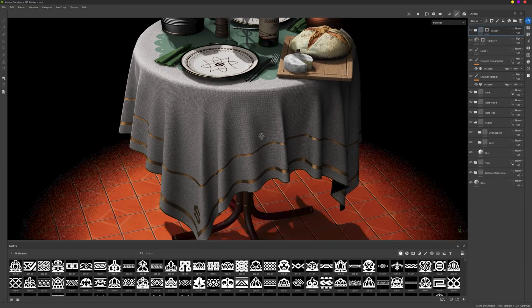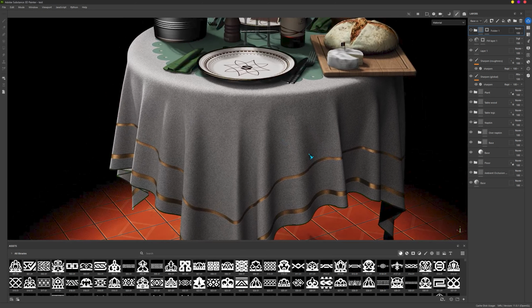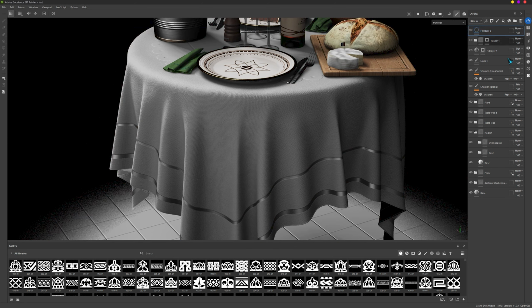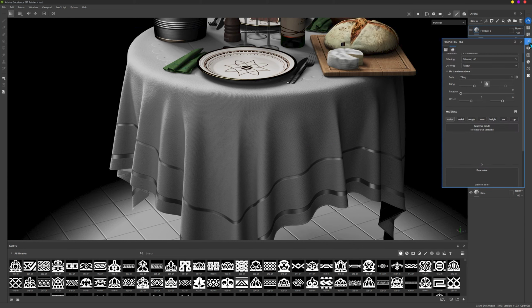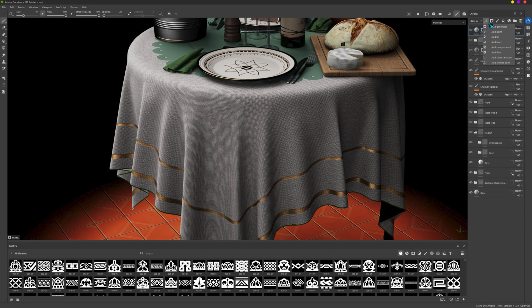We will add our Substance Designer pattern to this Substance Painter sample file, which is a dining table with plain fabric. Let's add a new fill layer. I'm going to use the base color and height. It's enough for these tiles. And black mask the layer. And we will add the fill layer to add our pattern.